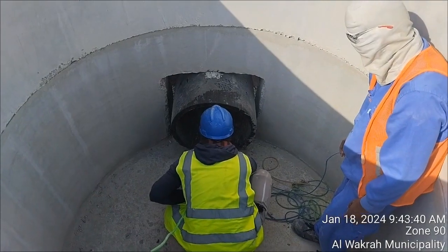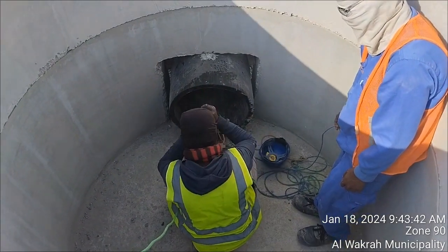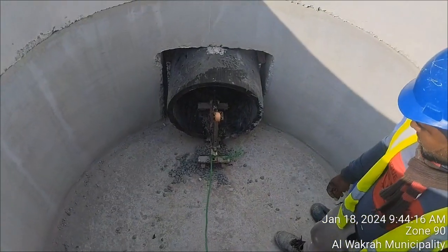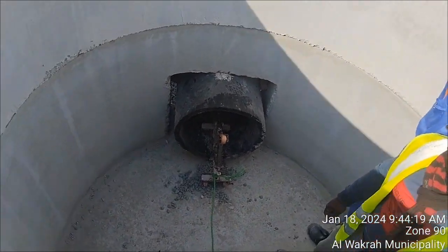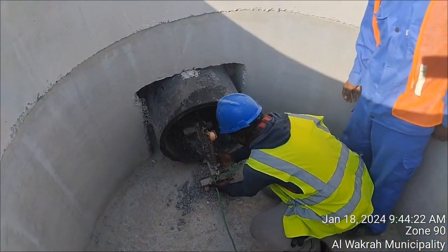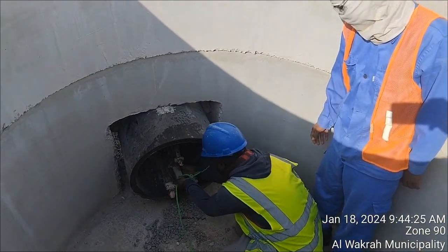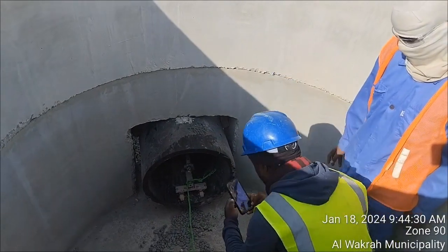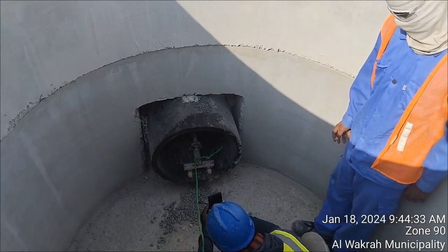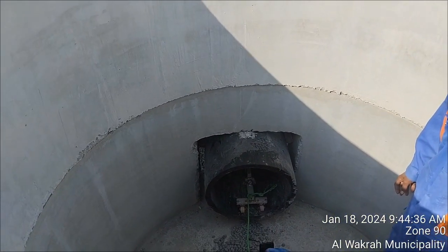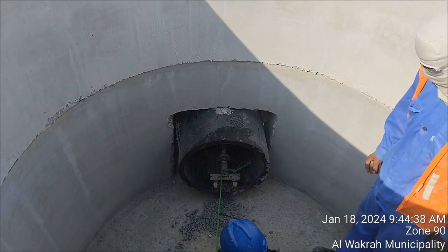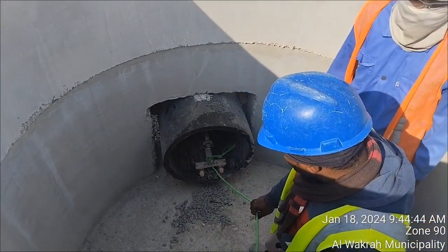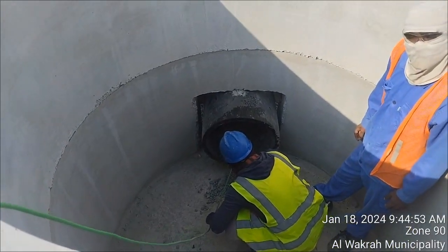As you can see here, this is the diameter of the pipe. This Mandrel will be inserted inside, and the other rope is also here. It will be pulled out to the other side. If this Mandrel goes perfectly from one manhole to the other manhole, it means the line is clear and workable for further activities. As you can see here, now we are going to pull this from the other manhole side, because there is another person sitting there who will pull it inside, and this man is just going to push it inside, nothing more to do, and he will continue with this.